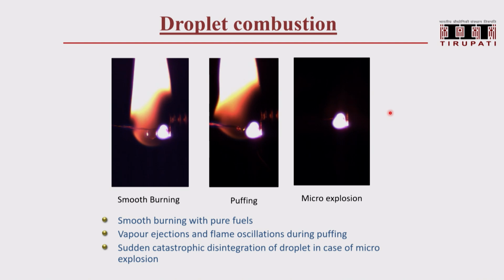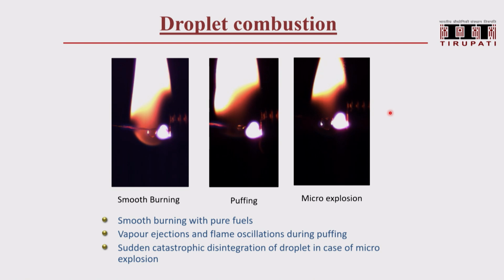The same thing we can use for fuels to our advantage. This is what we call a micro explosion: you mix low boiling point, highly volatile liquids into conventional fuels or high viscosity fuels, and they create this explosion.